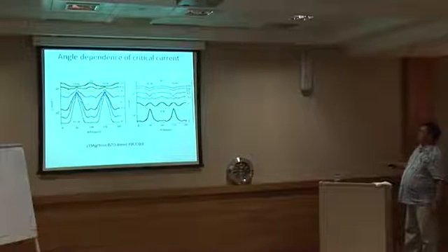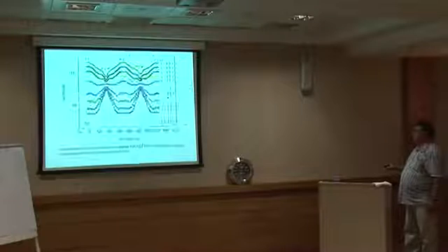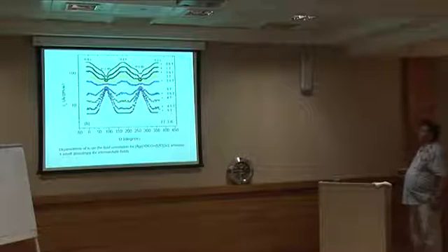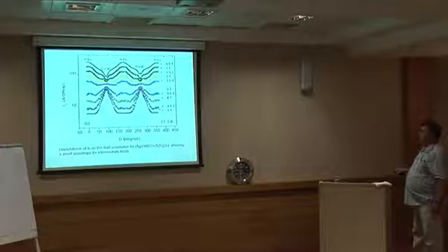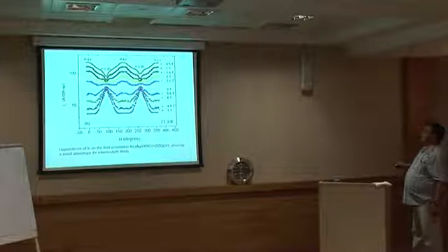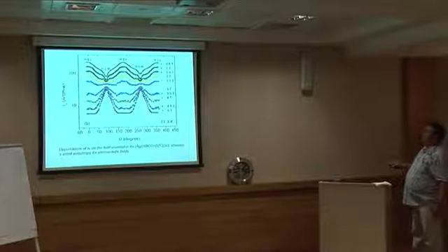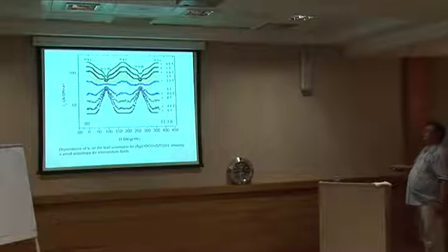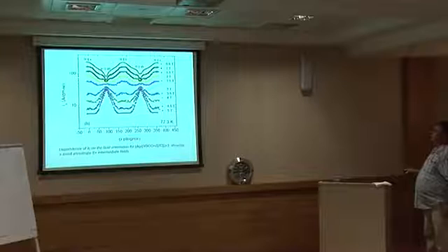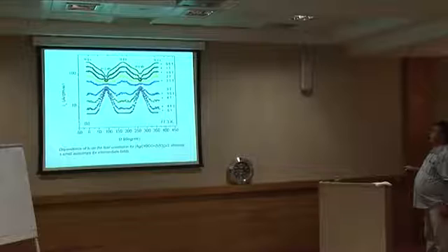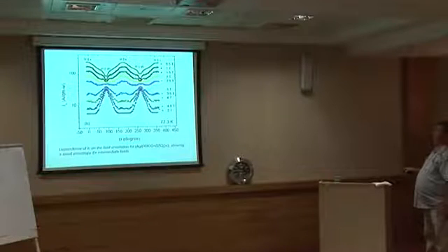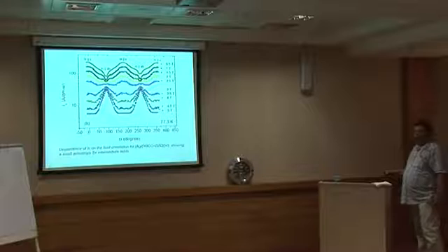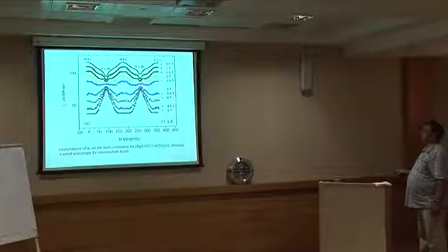This is some other images at 82 Kelvin. This is another 3-layer film, which you see the values, but now I plot it in the critical current as amps per centimeter width. So you see that if you need to work at 2 Tesla, you can easily put 50 amps in 1 centimeter width, and you will not surpass the critical current for that orientation.